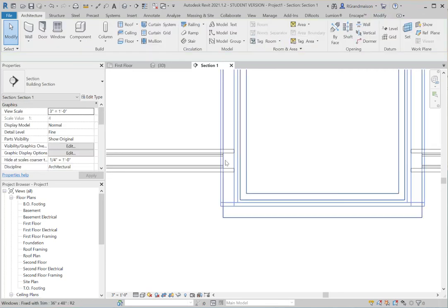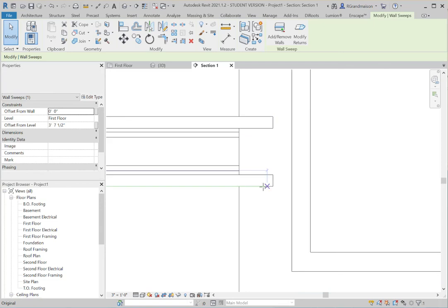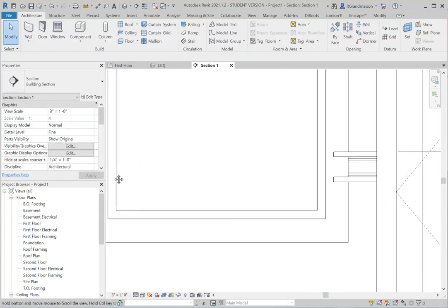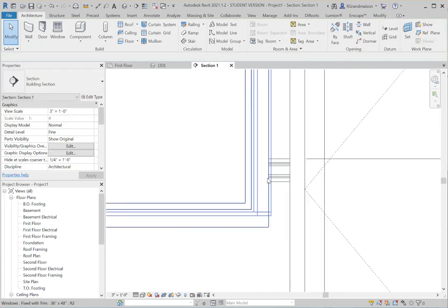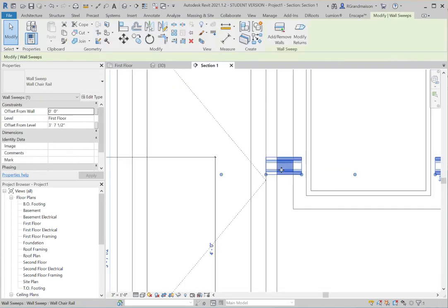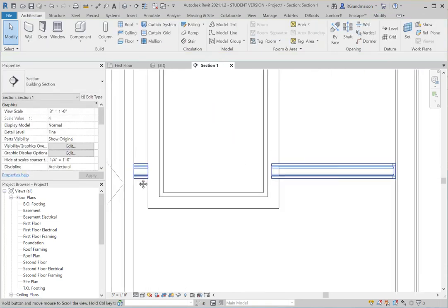However, again, the opening itself, the hole that's being made by this window template, actually is lined up with this edge right here on the object. This trim is applied over it. So you'd want to grab these corners and move them to the outside edge so you don't have any disruptions or any kind of weird, peculiar behavior happening between those. And you can do that on each one of these very quickly.